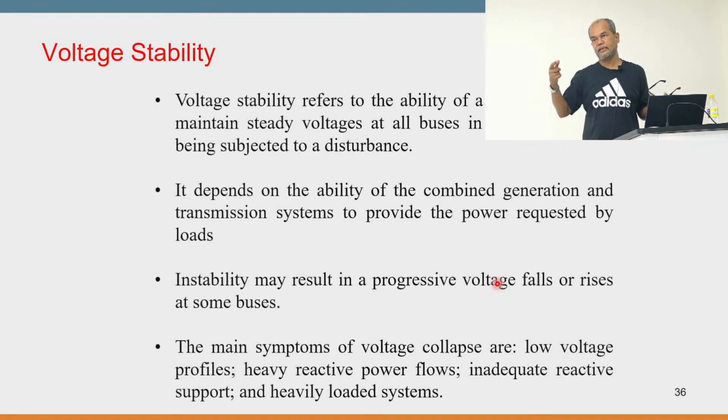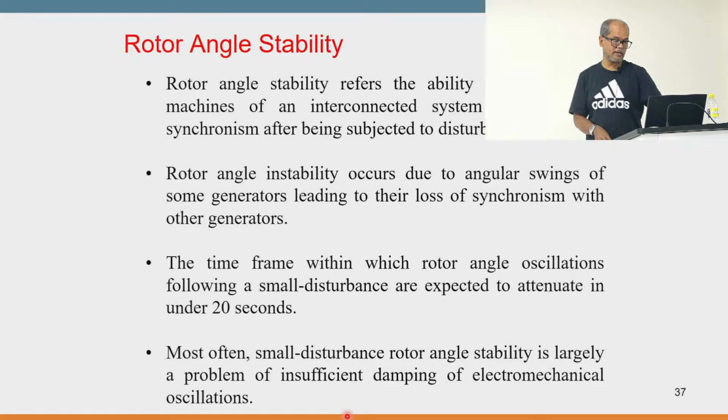From your experience you can find out from a low voltage profile, heavy reactive power flow in a load flow, inadequate reactive power support, or a heavily loaded system. If the system goes unstable, that might be a voltage stability problem.